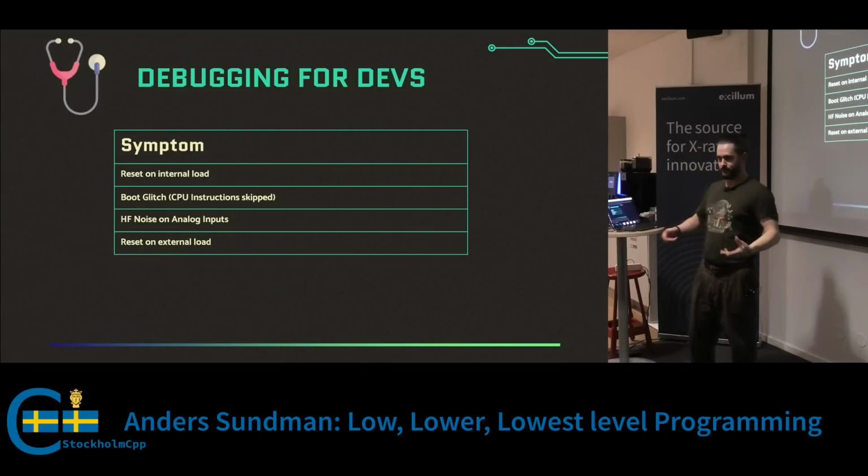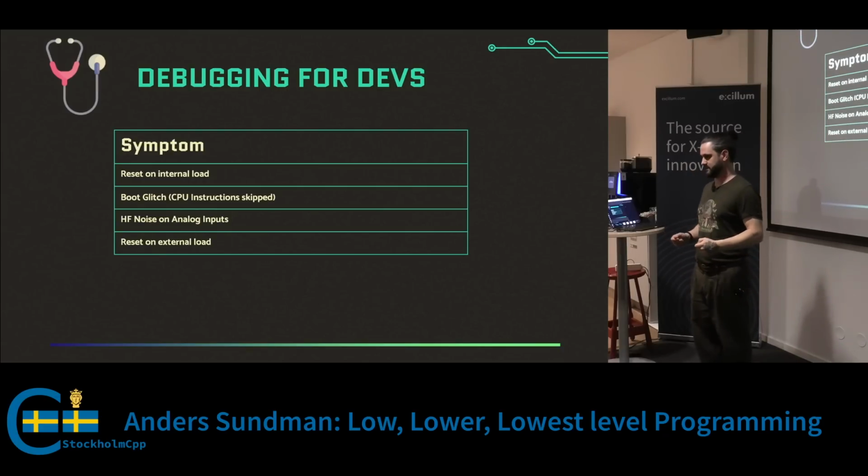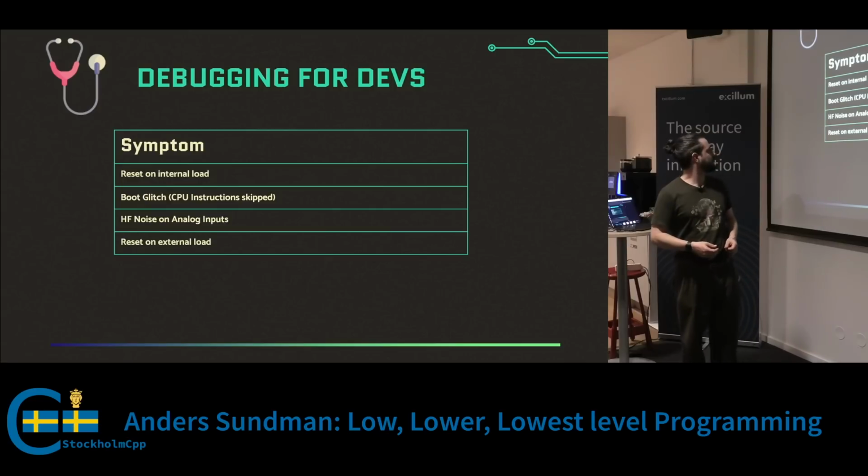Well, if you boot up the board and the CPU resets, and it does that not all the time but sometimes, it can be that it's power starving, and it could benefit from a little bit of a bigger decoupling capacitor.